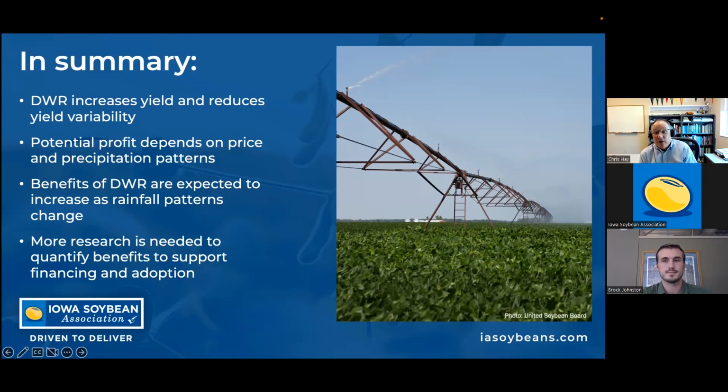And then we want a place where it makes sense to store water. So we're ideally not going to want to take really productive land out of production to create that storage reservoir. So if you've got an area that's either constantly wet, really low productivity, that would make sense to convert into water storage, or just some areas that aren't in crop production right now, but could be used for water storage, that's going to be kind of the ideal situation. So we minimize the cost of that storage by not taking productive land out of production.